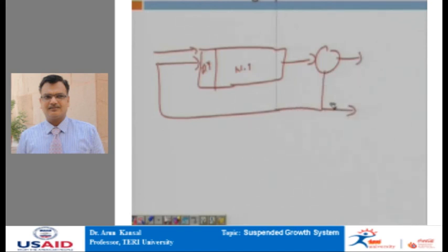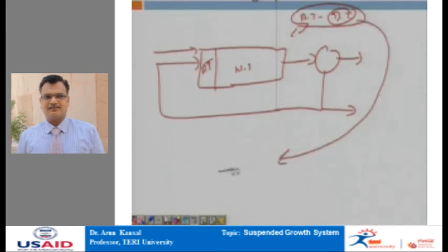Now, see, in the earlier slide I had shown you the aeration tank followed by the denitrification tank. Here in this slide I am saying first provide the denitrification tank and then provide the aeration tank. Why is it so? It is so because in the earlier configuration we are not able to provide food in the denitrification tank. Now, suppose I redraw this configuration here: this is the aeration tank, this is the denitrification tank, and the secondary settling tank.